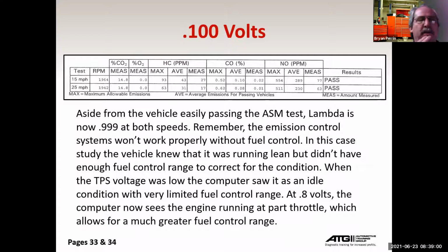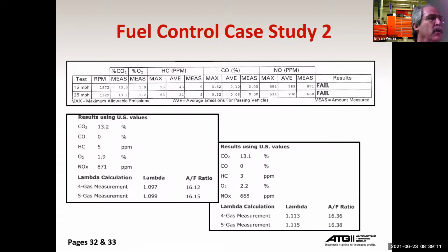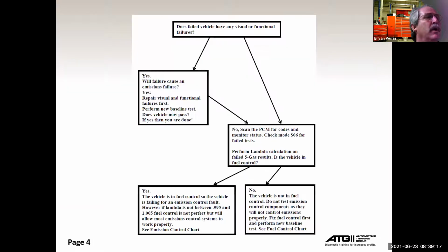This class is actually based on a book I wrote. And so it is fun and it walks through. The whole premise of the book was that I cannot infuse you with all of my knowledge. So I basically broke emission diagnostics into 3 flowcharts and then expanded each of those 3 flowcharts into basically making yes or no decisions. And so this was, is the vehicle in fuel control? If it's not in fuel control, go to the fuel control chart. Well, that's where I ended up with both those cars: I had to go to the fuel control chart.